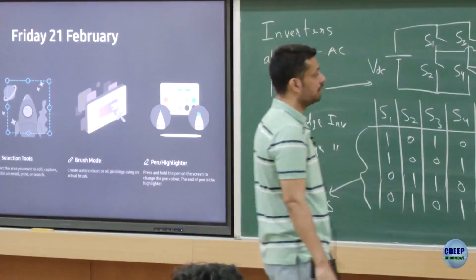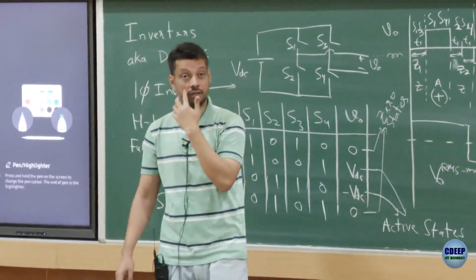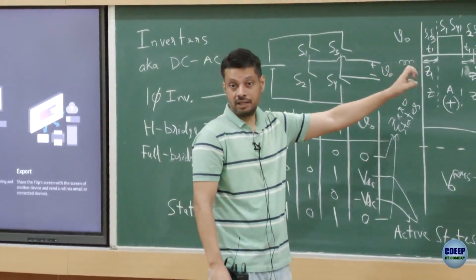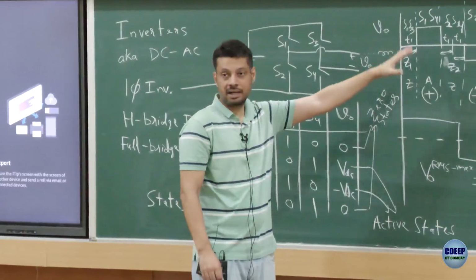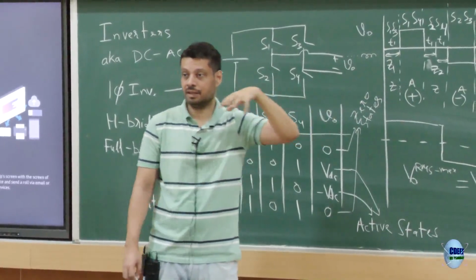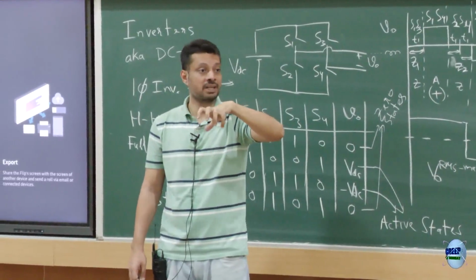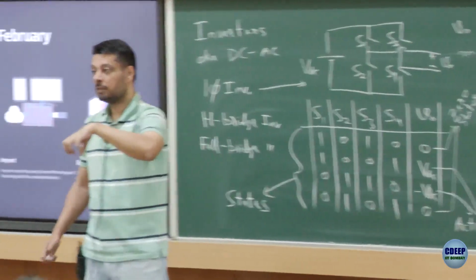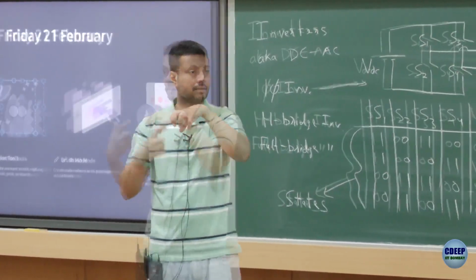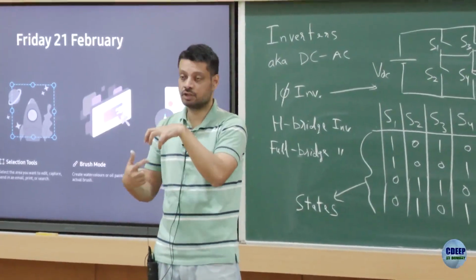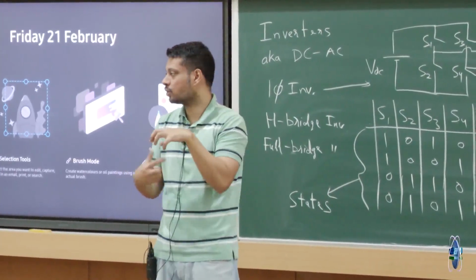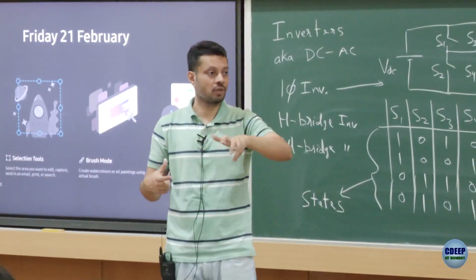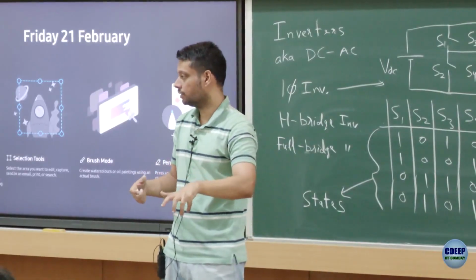Now if you see a 3-phase induction motor, if you supply this voltage to it, it would draw some fundamental current and it would also draw harmonic current. And the motor will not work as smoothly as you want it to, because it has a sinusoidal component, it's rotating, because the sinusoidal will lead to a rotating flux field which is also sinusoidal. But now there are these other harmonics also which would try to play around in that flux field and would create some sort of oscillatory or jerky motion of the motor.